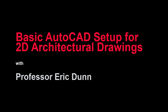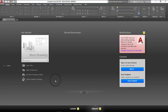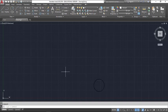In this tutorial, we'll learn how to set up AutoCAD for a two-dimensional architectural drawing. So I've opened up AutoCAD 2019 and I want to create or start a new drawing. So I can either press this button here, or I can go up and click the plus. And like many things in AutoCAD, there's multiple ways to do the same command. So I'm going to go ahead and click this big blue button. And I now have my area called model space where I can begin drawing.